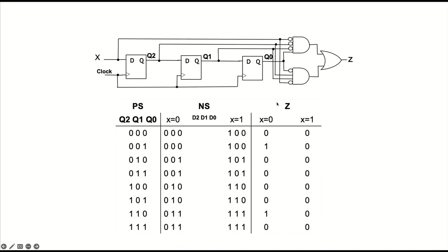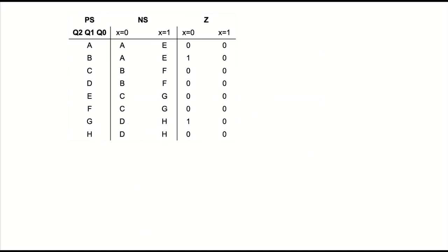Okay, so now that I have my state transition table, I can run Moore's algorithm, right? My first task is to divide the states by their output. So what's my first partition? Yes. B and G from all of the others. B and G have output 1, 0. All the others output 0, 0.